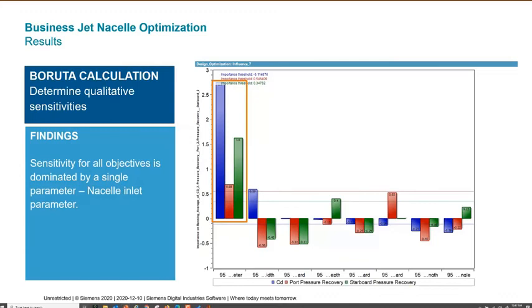Sensitivities are something that as engineers we're always interested in understanding: the relationship between our input parameters and our responses, and which ones are most significant. Classical sensitivity techniques just don't respond well at all to data that was generated by an optimization algorithm. There's a lot of bias in the sampling of an optimization algorithm. That's on purpose. It's meant to focus in on areas of the design space that it finds most interesting. And what that typically means is that any sensitivity calculations you might try to do, you really can't trust them. They're not going to be meaningful.